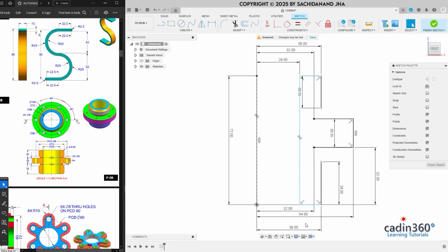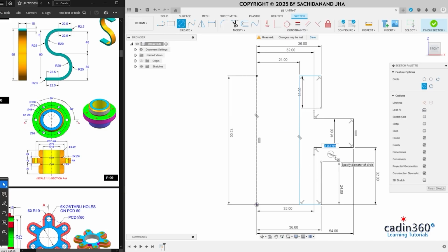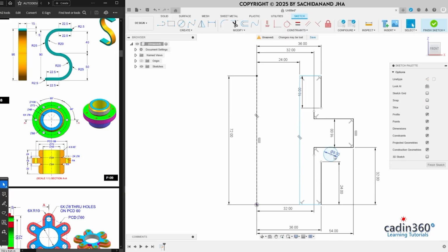Okay, now the next thing is we have to draw a straight line from this cut upside and from here to downside. Draw a small upside line, downside line, then create a curve profile here of radius 4, so there will be a dia of 8.